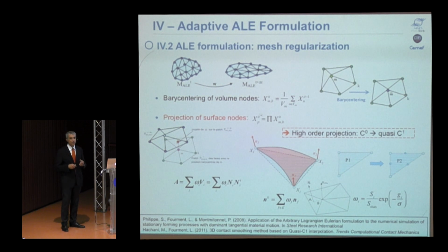The idea is quite similar to the one that we have used with the recovery techniques: before doing the interpolation, we are increasing the quality of the solution on the reference we want to transfer. In order to do that, we first compute the normals at the nodes. The normals are known at the center of the facet, but they are not known at the node. For that, we use a nodal vector voting approach, which has been developed in computer vision, which basically consists in doing some kind of averaging of the values of the different neighboring facets using a certain weight.